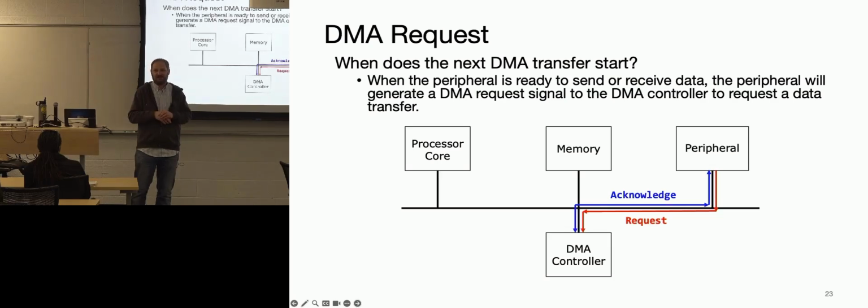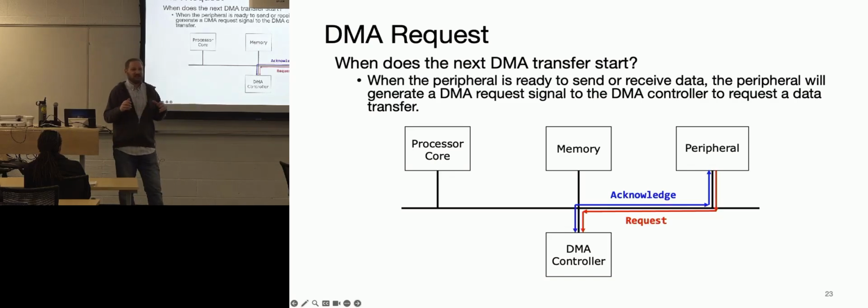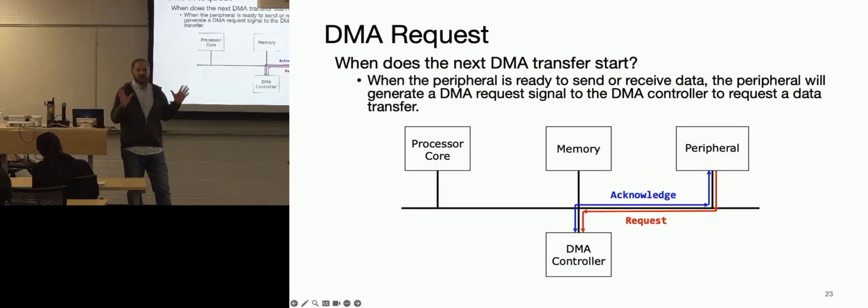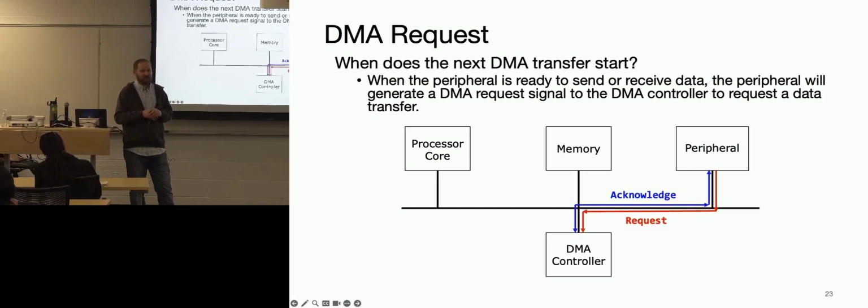Oh my gosh, you find that you did some weird clock tree and now you have to rewrite it from scratch. So what I'm saying is CubeIDE is pretty good, but be careful if you're doing really weird things. The WYSIWYG is going to fail you at some point, so be aware that there are limitations to that piece of software, because not very many people use it in reality. It's hard to support this thing.